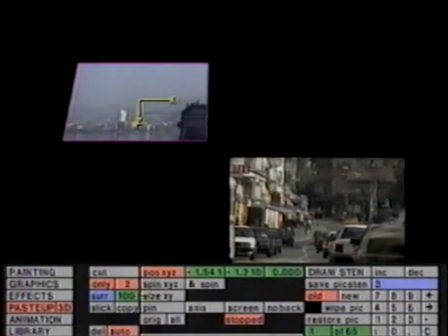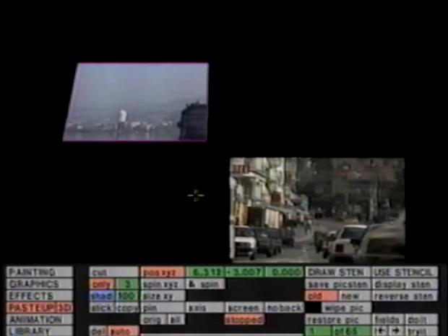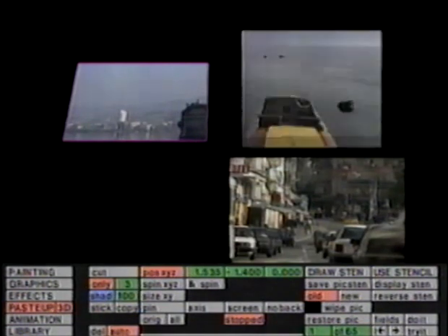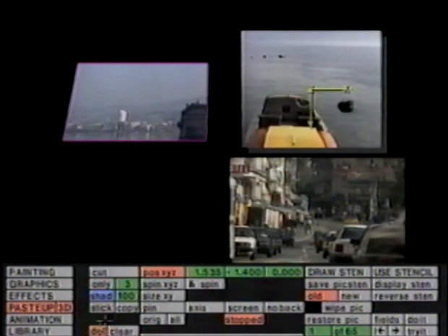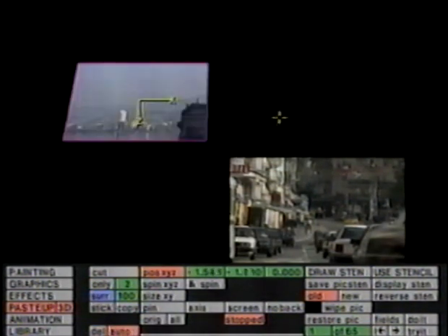To regain control of this layer, we need to select Only and enter the layer number, in this case 3. Now we can bring the layer back into view and delete it. Delete Cut will delete all the layers.